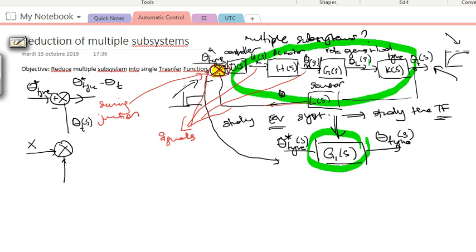Let's say you have X(s) here and Y(s) here. The signal that comes out of the summing junction is X(s) minus Y(s). It really depends on the symbols that you have in the summing junction. For example, here it shows plus on the left-hand side and minus on the lower side, so it means X(s) minus Y(s). If both show minus, then it is minus X(s) minus Y(s). If it's minus plus, then it's minus X(s) plus Y(s). So I think you got the idea.